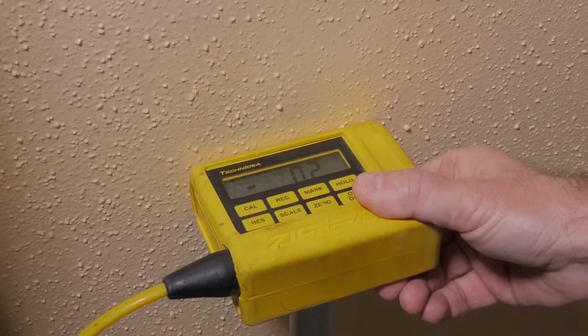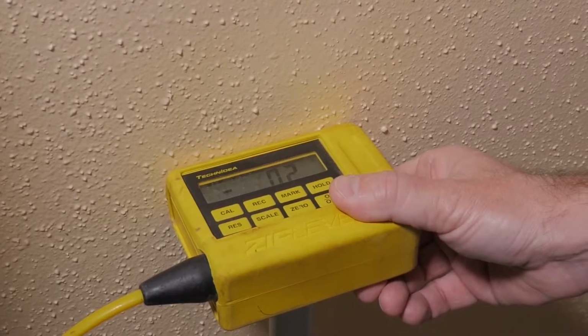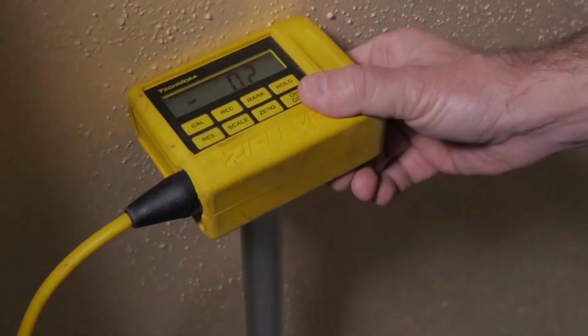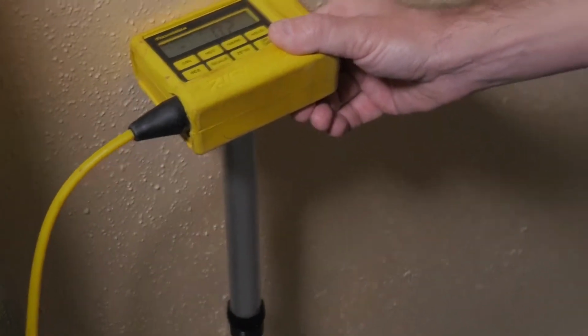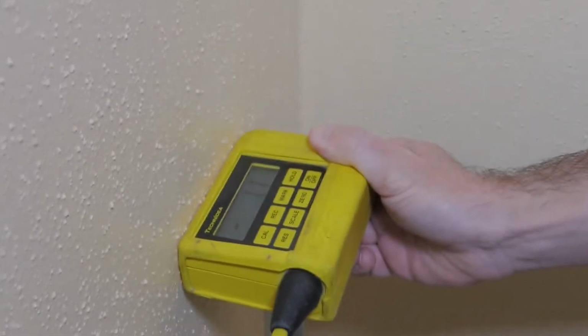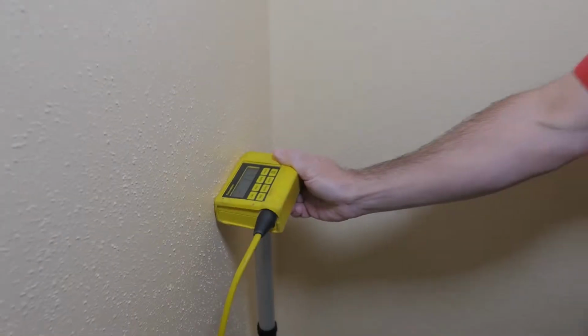Okay, so I can see that from my reference spot, this point reads 2/10 of an inch lower than the reference spot, okay? And so I'm gonna take it to the corner over here. Okay, so here we can see we're about 1.1 inches down. I don't know if you guys remember or not, but there's a crack right down the wall just on the other side here. So that's probably why that crack is right there, because this is settling.